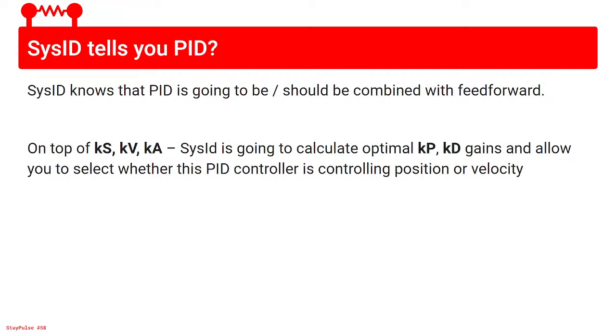What's the process of running sysid? Do you actually run it? Do you simulate it, or do you run it on your real mechanism? Oh yeah, you should definitely run it on your real mechanism. These coefficients will account for the dynamics of your system as well as inefficiencies. So it's good to run it on the real thing.